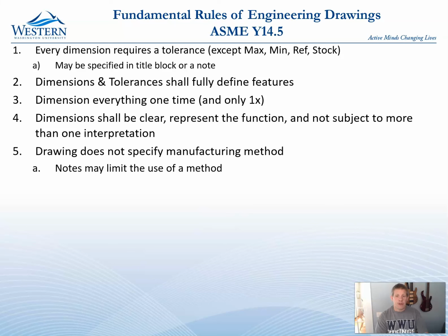Drawing does not specify the manufacturing method. So this is a change from older manufacturing processes. It used to be, when I went through school, that if you had a tapped hole that had a counterbore on it, you said drill to this size, tap with this tap, and then you would say counterbore to this size and then ream the counterbore to this size. Now you don't do that anymore.